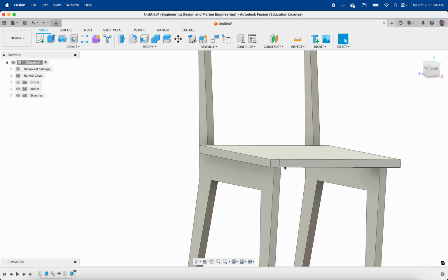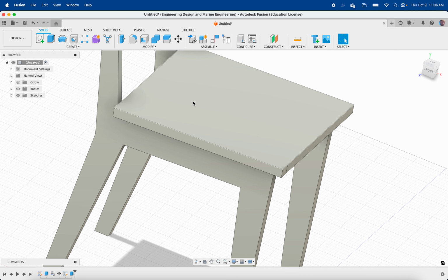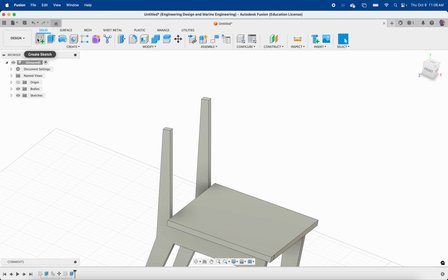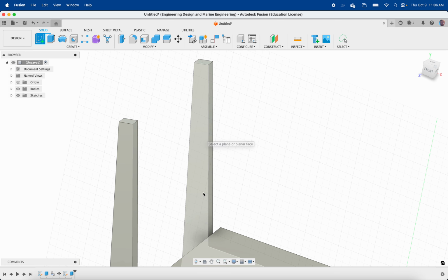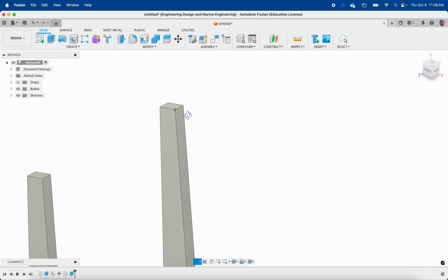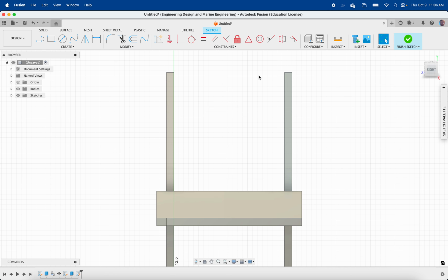I would do something to make this prettier, but I'm not going to talk about that right now. Round the corners or create a taper or something like that. Start a sketch on the back on either of those two surfaces, not on the side, and again, not on one of these yellow planes. You're going to start a sketch right here. Rezoom to get where you need.